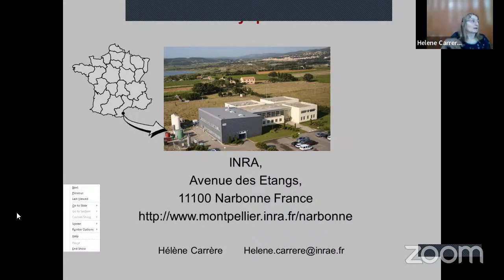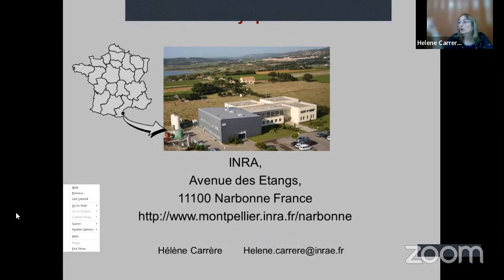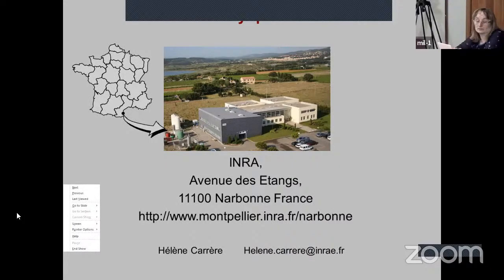Yes, well, I'm working on pretreatment of the waste to improve this and the energy recovery, but the problem is the cost. The anaerobic digester already has quite a cost, and you should add another cost. But also, most of the time, you can have the same results either with a pretreatment or by increasing the hydraulic retention time. So both points should be considered, I think.